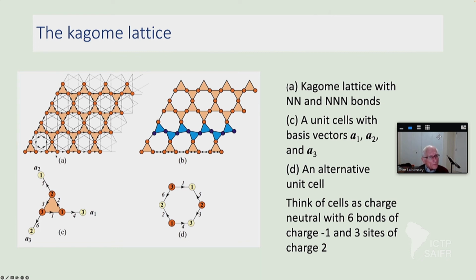And I can then ask, well, what does that tell me about what kind of modes I will have? So first of all, we know that for each state of self-stress in the Maxwell lattice, there is a zero mode. So what that's telling us is that there is a zero mode for each one of these lines that go like that, well, those that are under compression. So if I'm looking at the bulk modes, I can use the periodic boundary conditions.